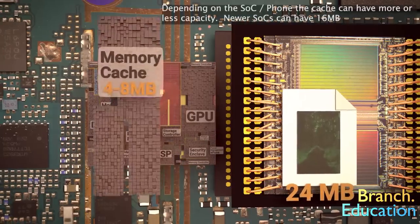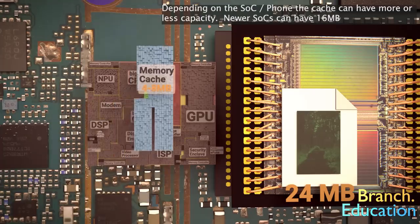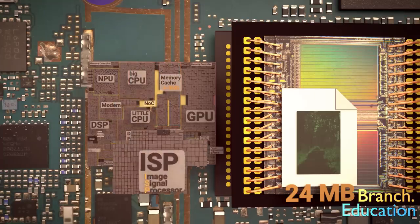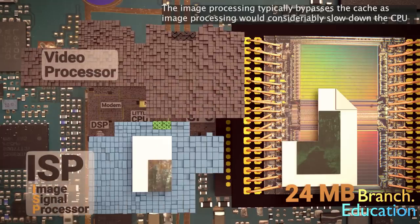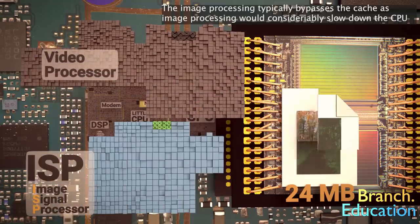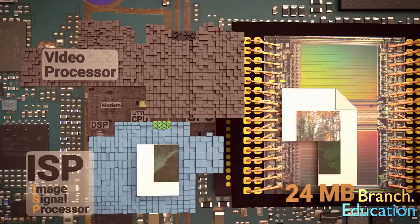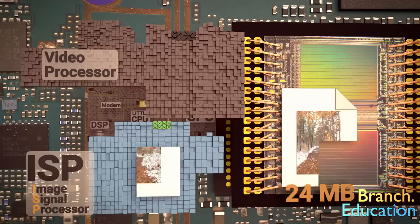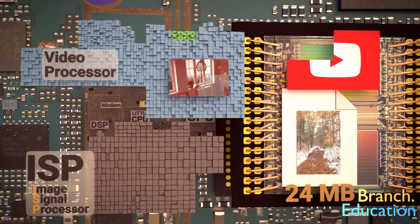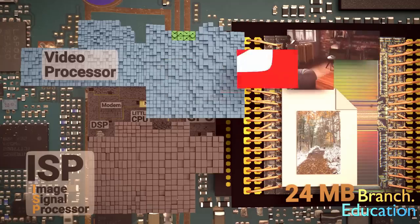However, the memory cache on the SoC is typically 4 to 8 megabytes and is shared among all the processes on the SoC. Therefore, when the image signal processor or the video processor works on a recently taken picture in order to make it viewable or to compress it, they can only work on small subsections of the overall image, leaving the entire image temporarily stored on the DRAM. This also happens while watching a video, playing a video game, or using pretty much any app.